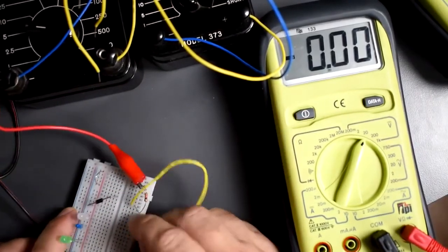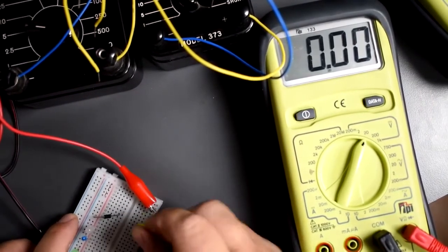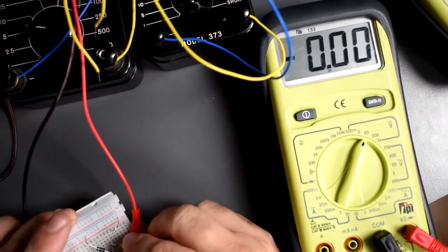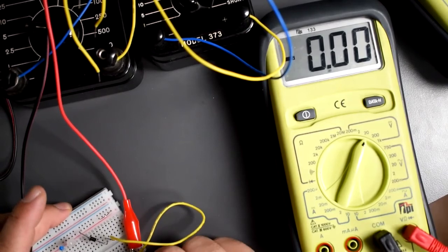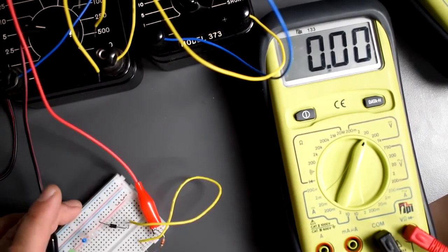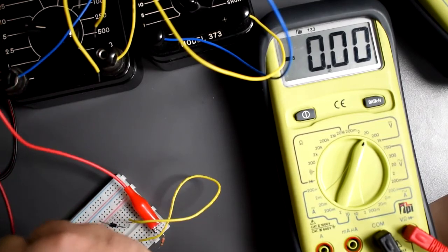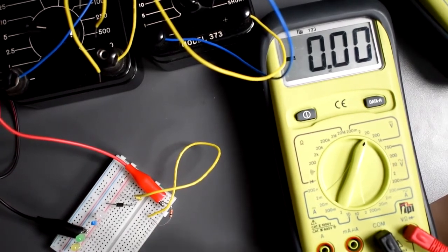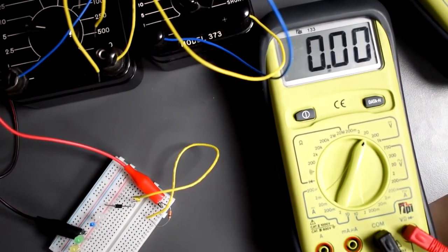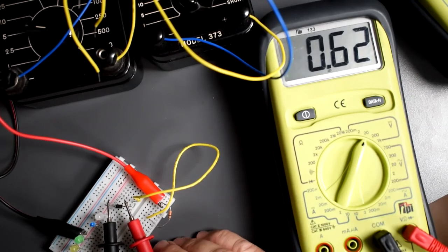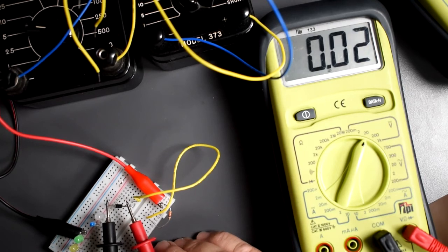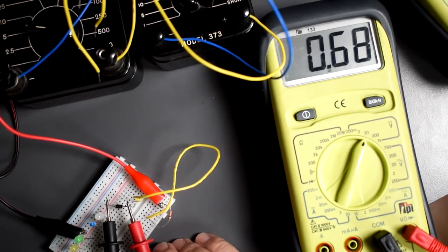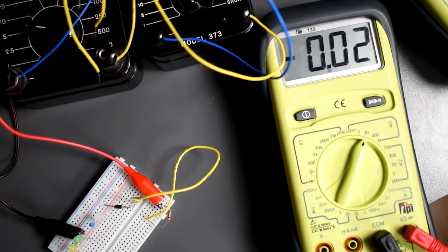This is just a general purpose silicon diode, and we're going to connect that in the circuit. Okay, I think we still have it connected. No, we don't. And we're just going to connect it anywhere in that rail. So now we should have current flowing through this diode and through this resistor here. So let's see what the voltage is going to be. Oh, we got 0.69, so it's like 0.7 volts. That's right. Okay, so silicon diode should have 0.7 volts.